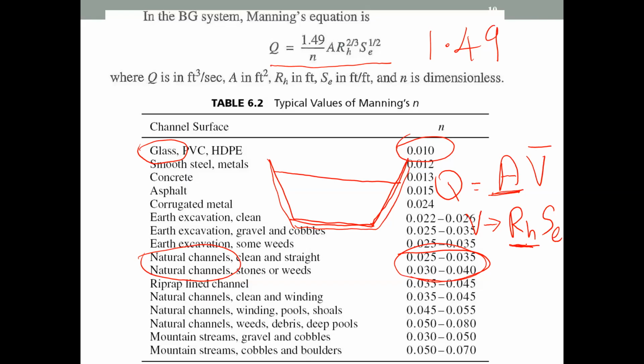So nowadays you have these sophisticated calculators and computers so that the iteration can be done very easily. But in earlier times, they didn't have this kind of facilities. So what they did, probably you remember the Moody diagram. The Moody diagram is used to find out the friction factor based on the Reynolds number and the relative roughness.